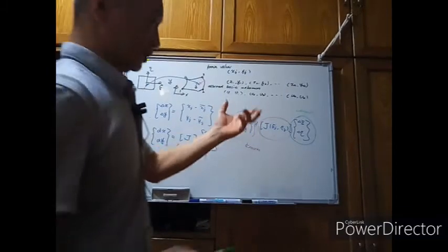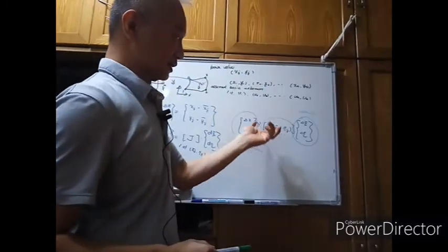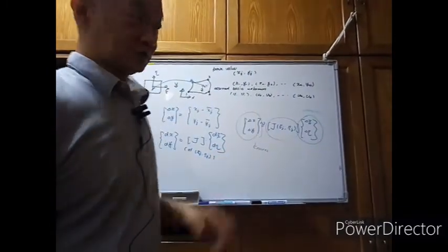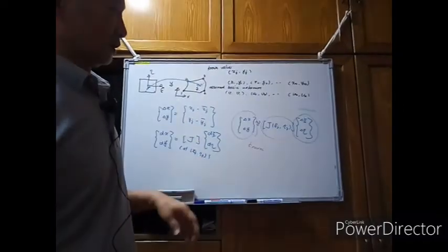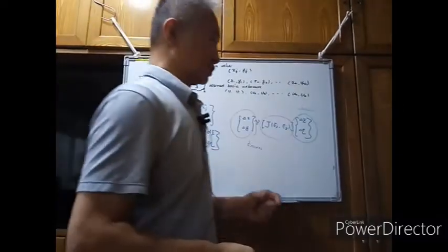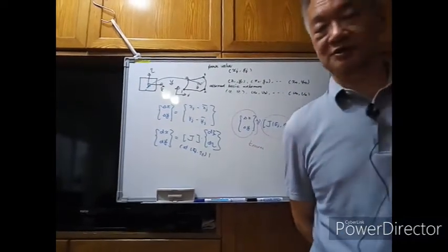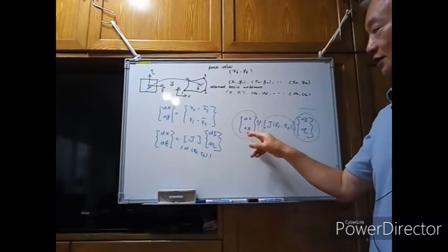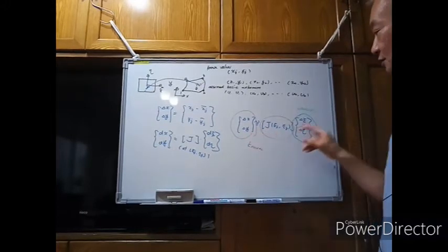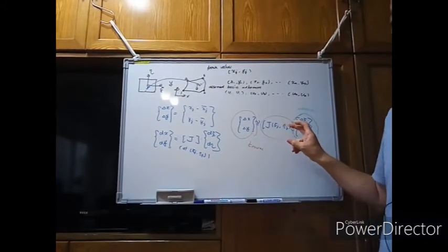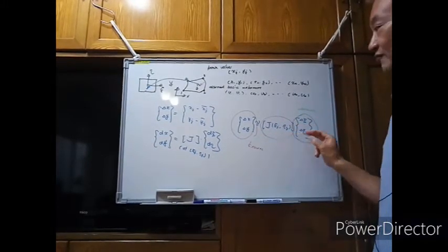And also we have the trial Cj and eta j, so the Jacobi matrix can be calculated. For plane stress problems, the Jacobi matrix is a 2x2 matrix, and the delta x, delta y is a 2x1 vector. The delta C and the delta eta are also a 2x1 vector.